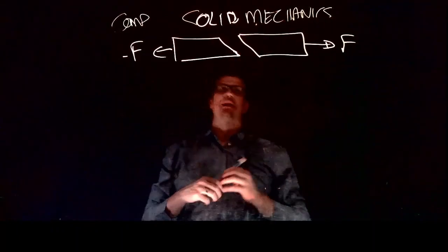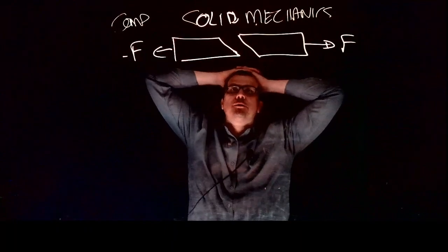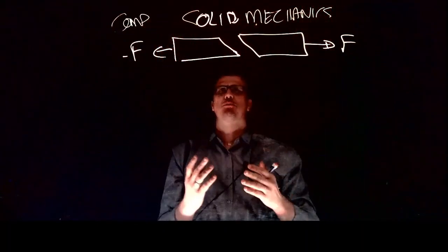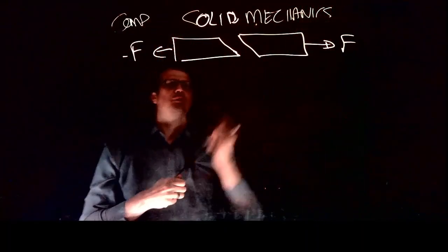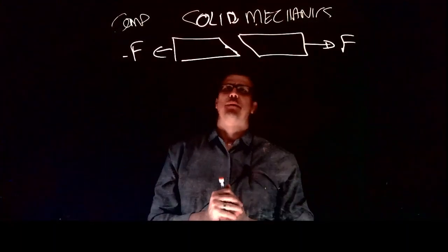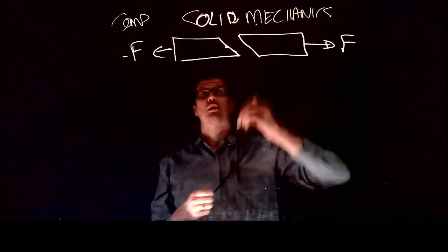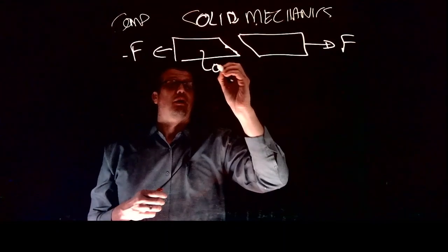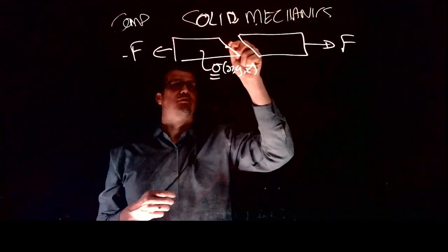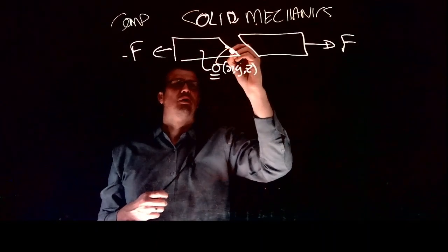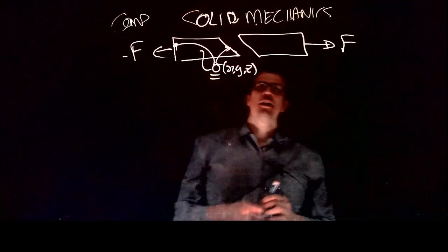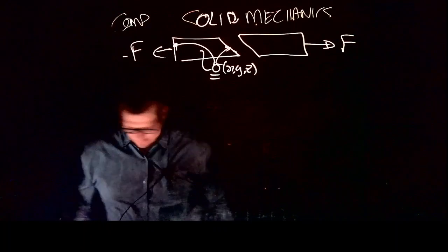So breaking that into two problems, we zoomed out on this face and had an average idea of what the stress components were, what the normals were, and that was good. Then we zoomed in and said, let's look at a point and see what happens at a point there, and we could make sense of it. So in the end we could have a stress tensor in X, Y, and Z that could actually relate to tractions on the face as well. So it didn't only relate internally, it could also relate to things on the surfaces. We know how to relate it. That is the important aspect to understand. So that's step number one.